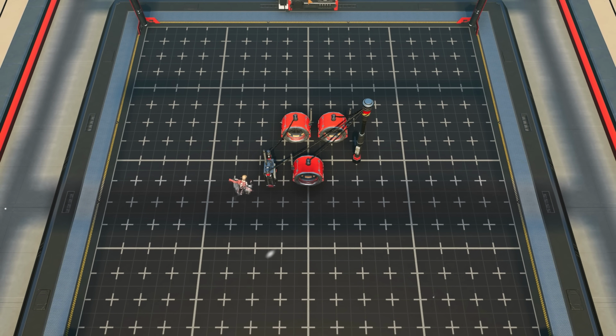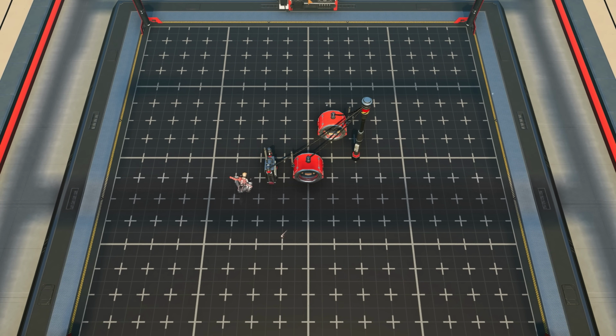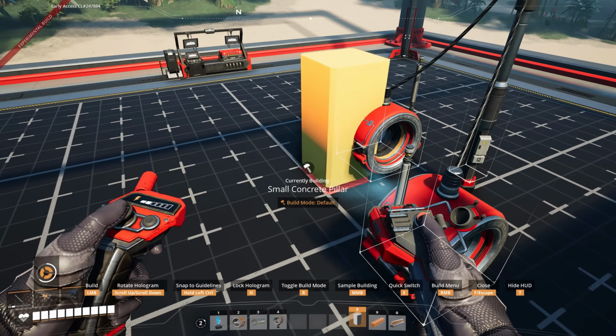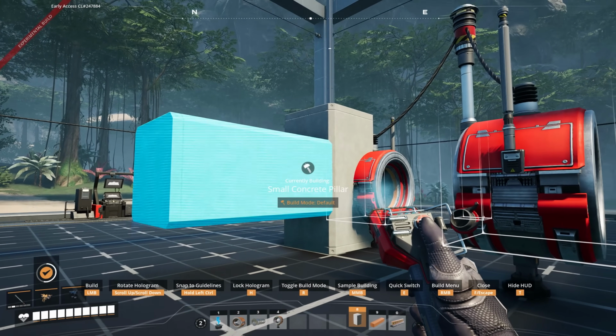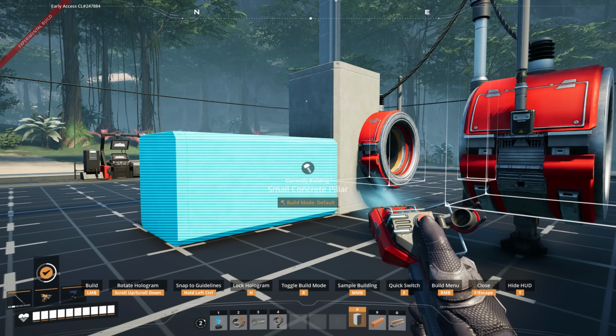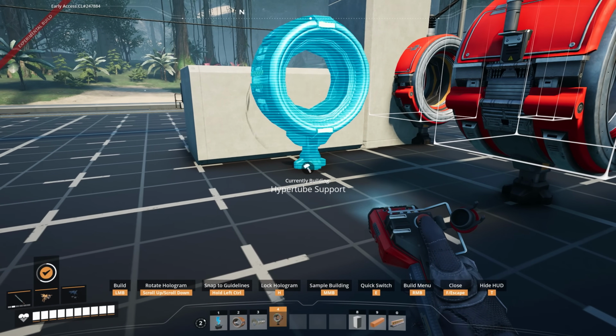While you can move the priority route in a whole metre, it's not the most aesthetically pleasing one. For a more symmetrical finish, you can use pillars to place the switched entrance slightly less than 2 metres off centre. First we place one pillar off to the side, in line with the line that we want to move across. By holding Control, we can move this to anywhere up and down the pillar, as well as rotate it if we need to. So let's place it down the bottom so it's running along the surface along the line that we want to move our entrance.